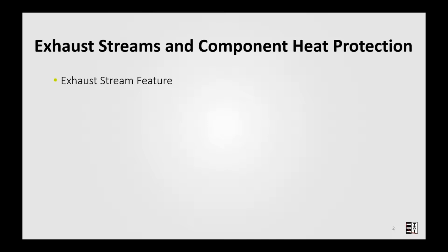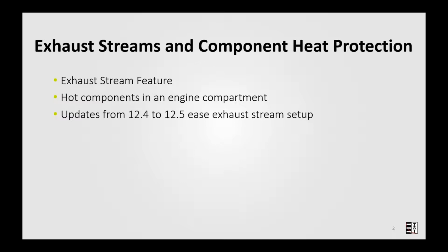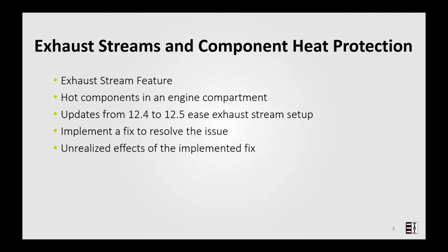All right, for this demonstration, we'll address some hot components in an engine compartment, and then we'll take a look at some of the updates that were made to the exhaust stream feature in TAITherm version 12.5. We'll then take a look at implementing a fix for our hot components, and we'll see if there were any side effects that may have come up because of it.